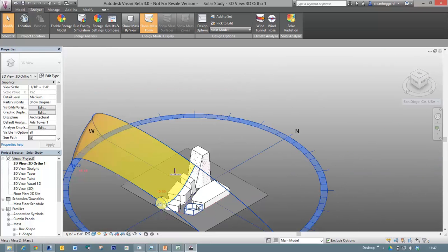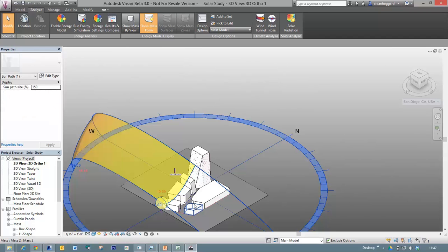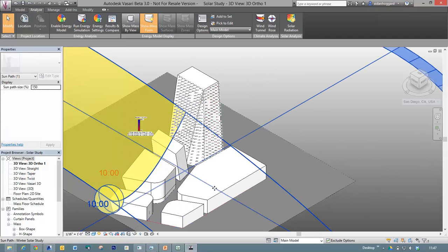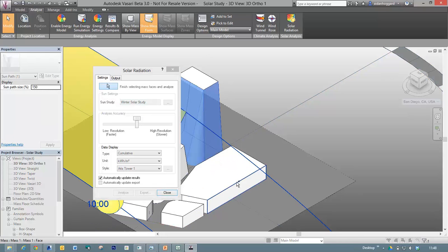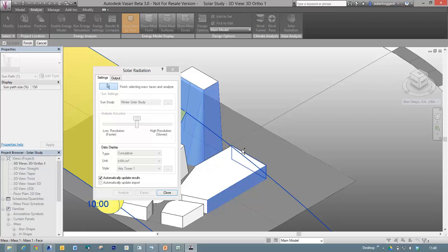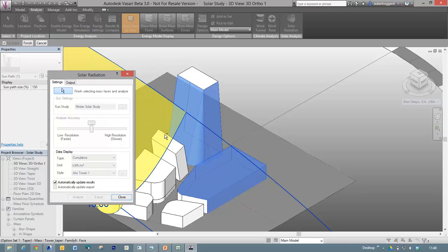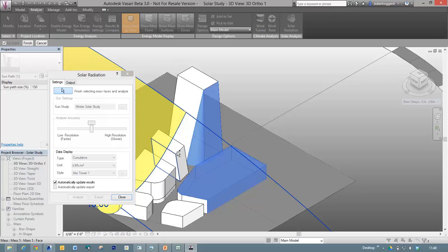The other thing you can use this for is if you're considering putting photovoltaics, so solar panels, onto a building facade, then again, this can be very powerful, because this time if we select our roof surfaces, just use tab there to, if you're struggling to get the correct face that you want, if you press tab, it will scroll through different faces.